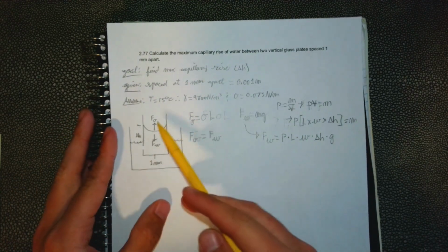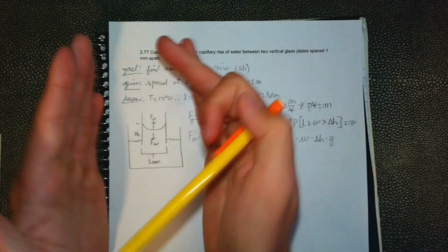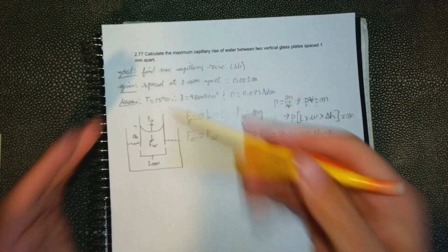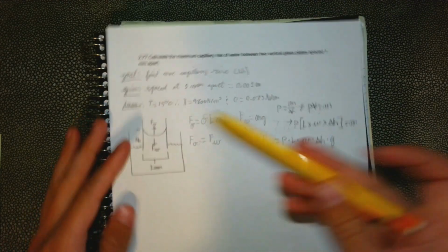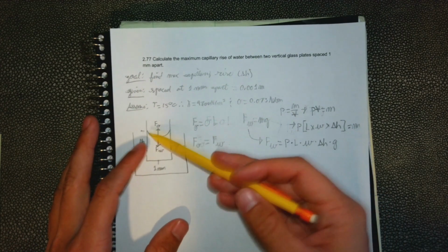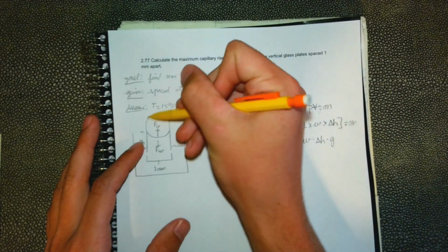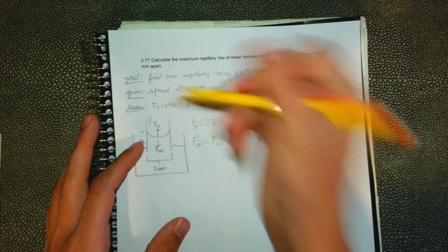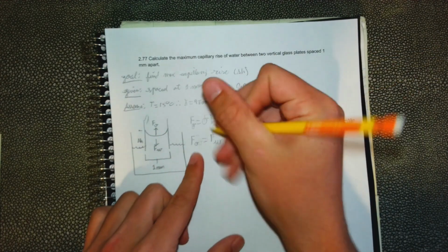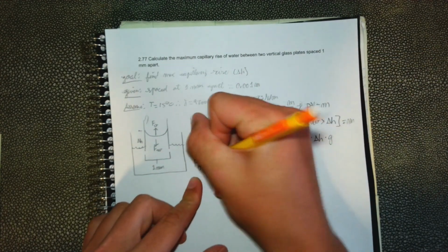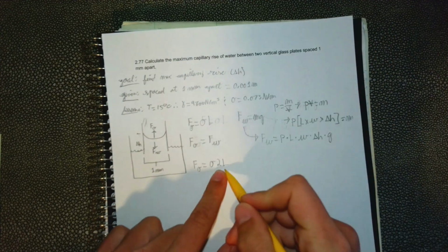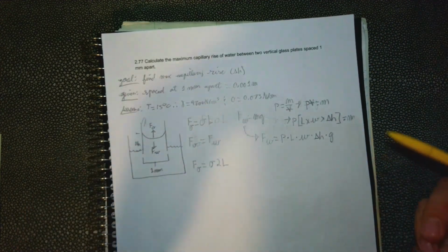So when we're looking at this, what is going to be the wetted perimeter? It's just two walls. There's nothing in front. We're not taking a cross section and looking at this. It's literally just those two walls. So the perimeter is just going to be the length, how deep this goes back. See what I'm saying? That's going to be the length. So the wetted perimeter is just going to be 2 of the lengths, right? Because it's just 2 walls.